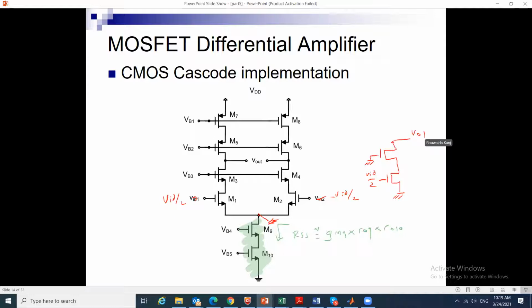I know how to find the gain for this circuit. Then this upper part here, which has a DC bias, is coming from a cascode current mirror. So for this upper part, I only care to find the effective loading, its effective RD or its effective R load on my